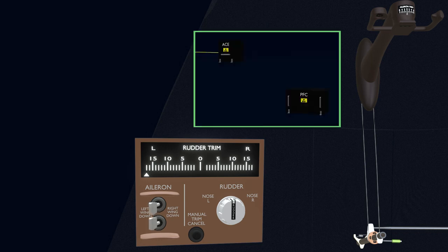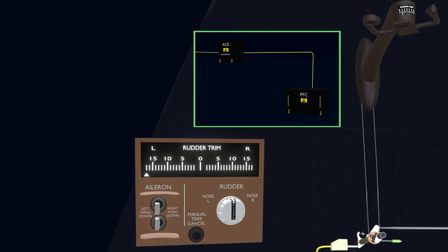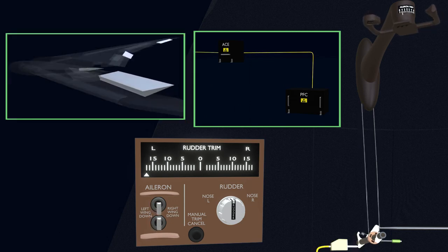When the trim switch is used, it sends a signal to the primary flight computer to rotate the control wheels. The PFC acknowledges and operates the aileron trim actuator. The control wheels are rotated until the switch is released. The wheel rotation results in flaperon and aileron deflection, just like a manual input. The trim actuator will now hold the control wheels in the trimmed state, until a new trim input is given by using the switch again.